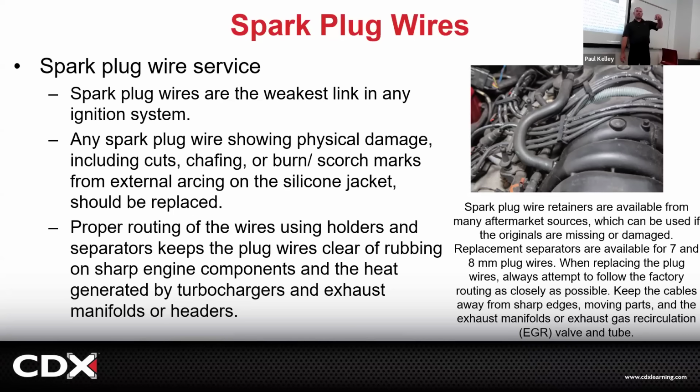So if you have spark plug wires where the insulation's kind of broken down and you have a cap and a rotor that are not sealed real well, especially on those Hondas with the distributor from the side, anytime you get water on there, remember path of least resistance, the secondary voltage is like, you know what? I'm not going to go all the way through that wire and then jump a gap on the spark plug. I'm going to exit right now because now there's water there and it's made the path to ground easier. So all your secondary ignition voltage just goes through the water and it arcs to ground right there.